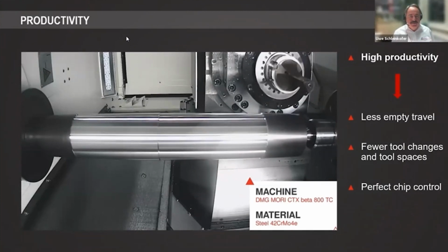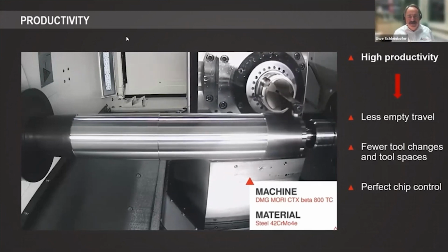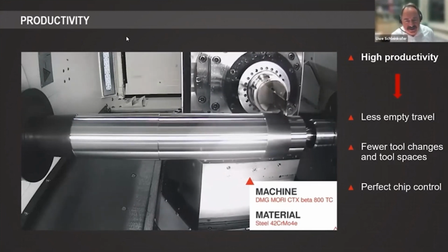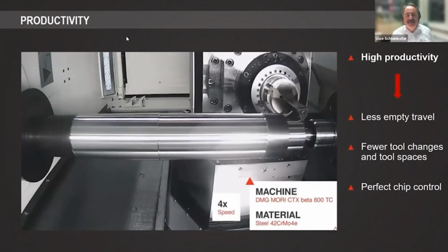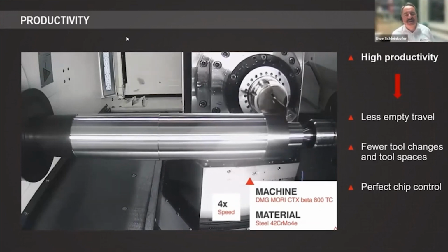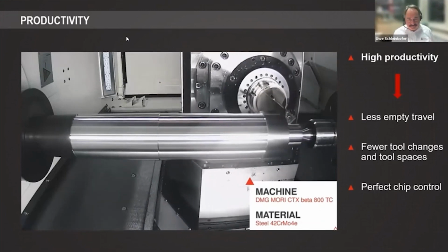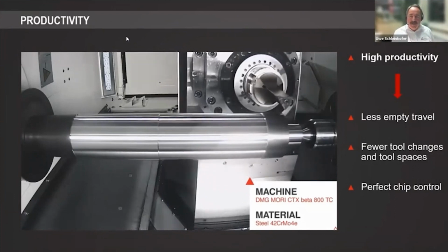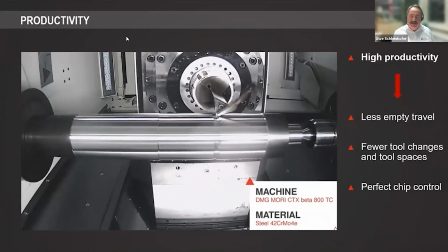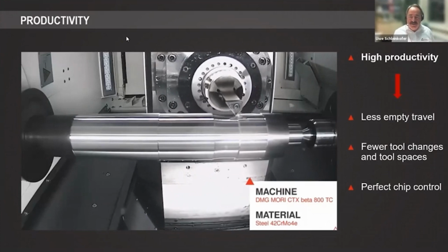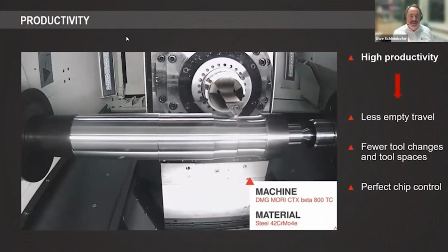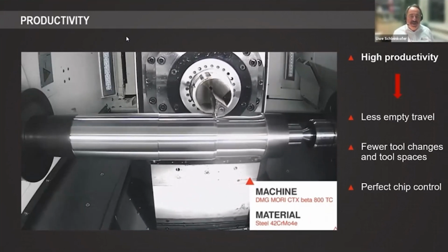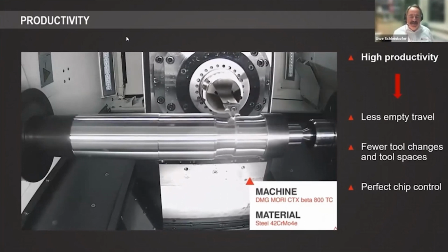By the way, we look from underneath to the top of the machine. So the camera is lying on the floor of the machine, which gives, of course, a very nice chip evacuation. You see the chips are falling directly to the camera. So we are preparing now a steel shaft, and we do that in various steps. And you see now, like the FreeTurn tool is moving back and forth to open this pocket.